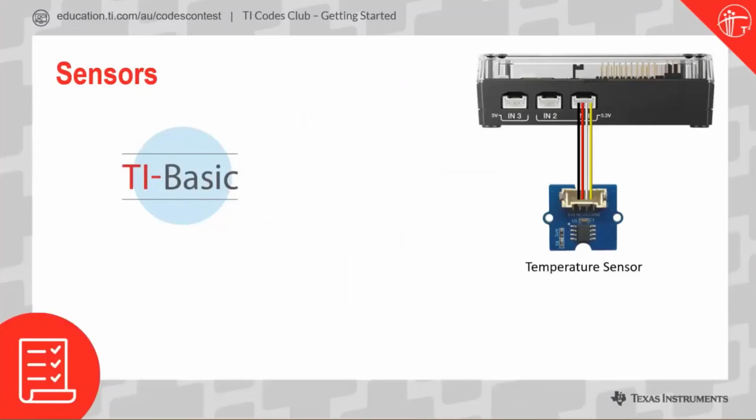Thank you. All right, while Brian was talking there, you might have noticed I'm now looking at the side of the TI-Innovator hub, and we can see it says IN 1, IN 2, and IN 3. That's IN, not natural logarithm. So we've got input 1, input 2, and notice input 3 has its own little surround there. So that can handle sensors up to 5 volts, whereas input 1 and 2 only go up to 3.3 volts. So that's our sensing. But these are all plug-in ones.